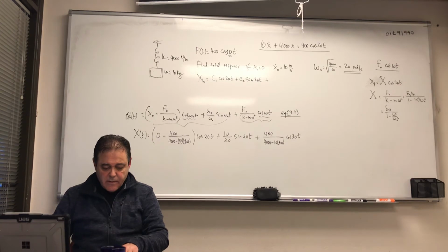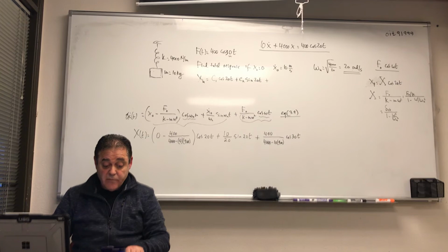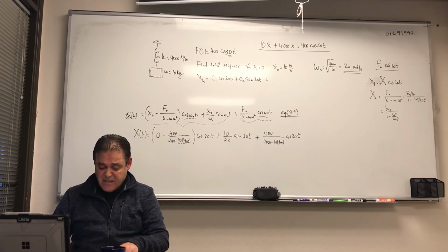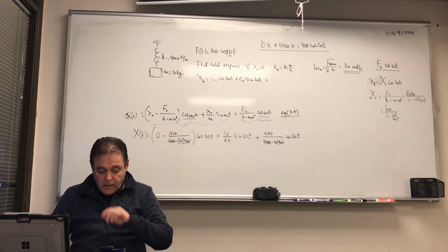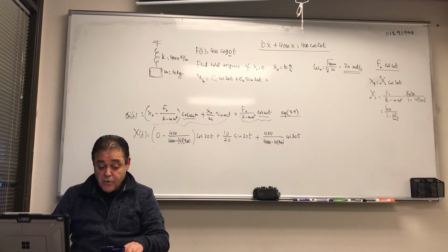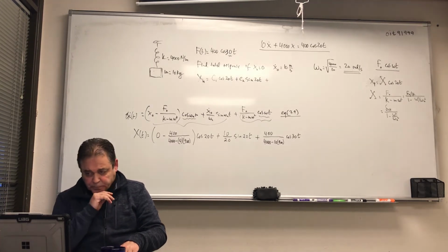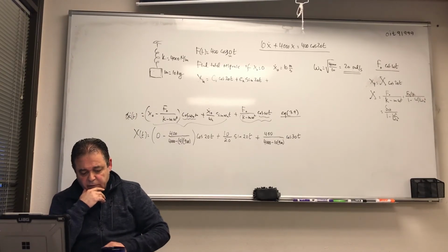So you've got a mass weighing 100 newtons and a spring with a stiffness of 2,000, and the mass is subjected to resonance by a harmonic force. F of t is equal to 25 cosine omega t, which means omega n and omega are the same. Find the amplitude of the forced motion at the end of a quarter cycle, at the end of 2.5 cycles, and 5 3/4 cycles.